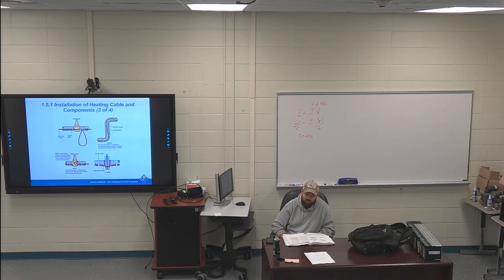So you have to take whatever your load is, say your load is 20 amps, multiply that by 125%, and actually size your overcurrent devices, which is your circuit breaker and stuff like that, for 25 amps rather than 20 amps. You have to size up because this is considered continuous duty, since it has the ability to be on for 3 hours or more at a time.